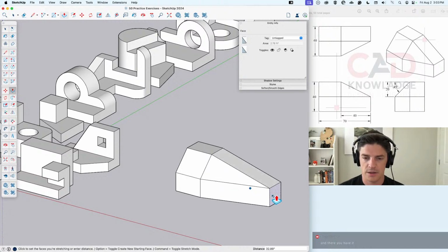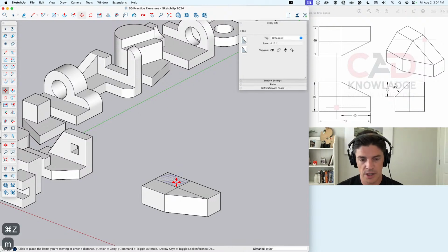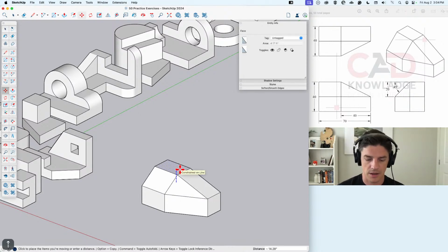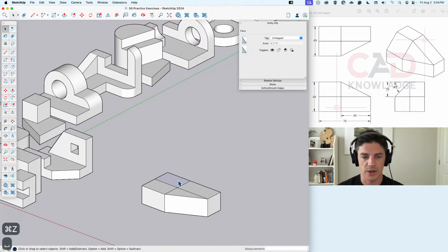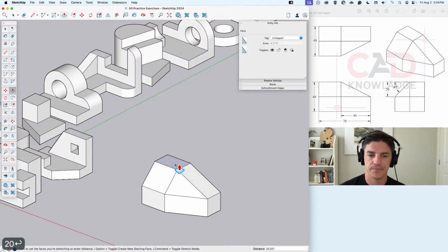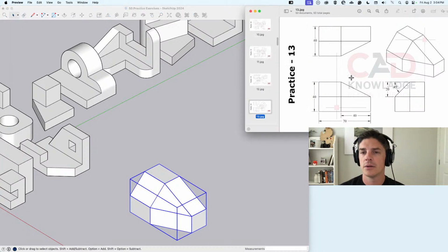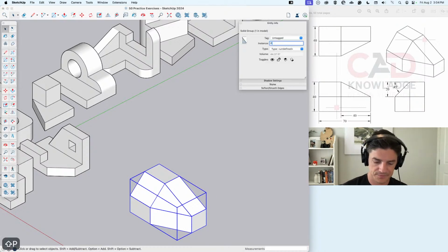Yeah, that's interesting. So it's the same thing, but you get two ways of moving, but only, like you said, you'd have to lock the blue direction if you're using Move for auto fold. But if you're using Push/Pull, it only works in a perpendicular direction, right? Yeah, because it's orienting to that face, so that face is sitting flat on the surface. So then you don't have to lock because it only works in that one direction. Cool. I like that we spent a little longer on this one, just a teaching moment.